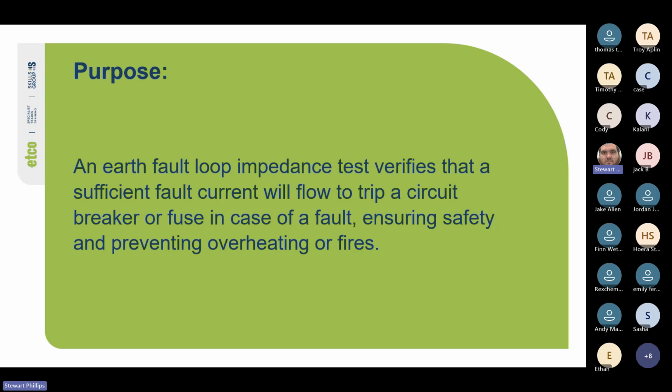We're also making sure it's not so high that our gear is going to break. So at the switchboard, if we have, say, 10,000 amps worth of fault current possibly, and we've only got a circuit breaker rated for 6,000 amps, we need to look at upsizing it. They generally come in, the biggest I've used for domestic, where people are living, was 10 kA. But on the network, you'd be dealing with HRC fuses, which are like 80 kA plus. So be aware of that.